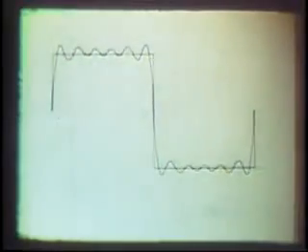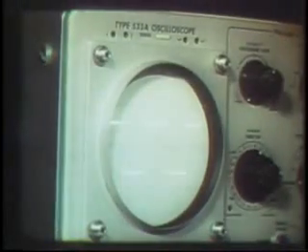It would require an infinite range of harmonics to produce a truly vertical edge and an actual sharp corner. This situation is physically impossible to produce. But waves can be generated that are very close to this ideal. A wealth of information, then, is contained in a single square wave. Due to the harmonics involved, this single waveform contains a wide range of frequencies.